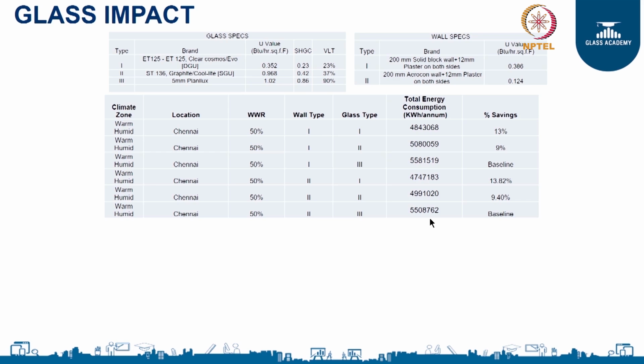So you can combine these simulations, which are energy simulations, with the daylight simulation, and you can match the two and see how you can improve your daylight and at the same time use a lower SHGC. That involves a lot of studies on sun path and trying to align your building to the right kind of orientations, so that you get the optimal light inside the building, right? So all these studies can give you a fair bit of insight on what type of material to choose from when you do your energy studies.